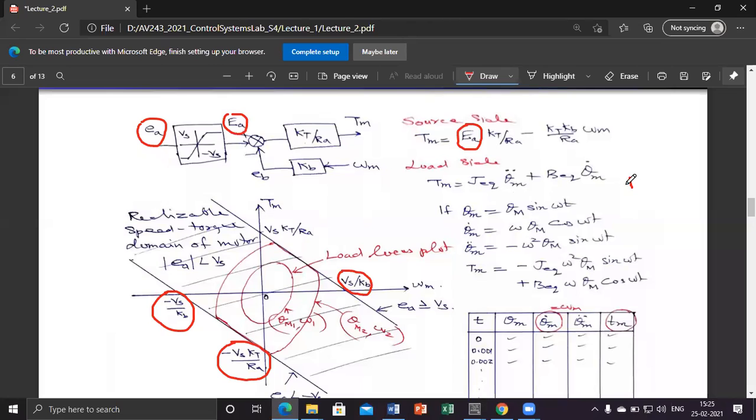Plus or minus 5 degrees is the maximum amplitude, so we will not deflect the engine for this maximum amplitude with the maximum frequency. That will not do. For example, we'll apply the maximum frequency of 5 hertz only for 0.5 degree, 10%. When you make it 20%, you'll further reduce like that.